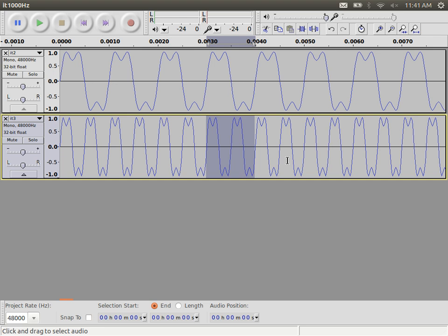The third component, 5,000 hertz. Do you see some pattern there? Do you see the pattern in the signals that I'm creating? 1, 1/3, or 3, 1/5, 5. The reason for this is to create this structure, which we'll see shortly. The more we add using this pattern will eventually lead to a square wave.